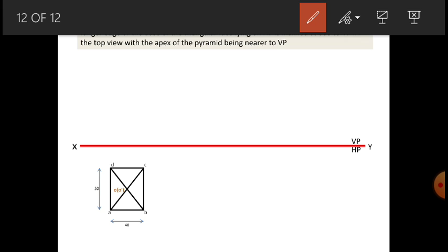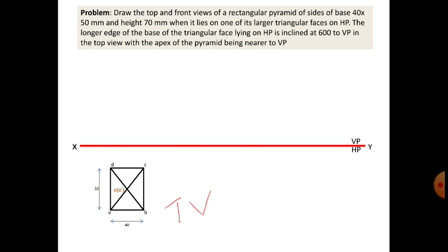Now this is your top view, right? The pyramid has its vertex, or the apex, where all the edges meet at a point, that is O dash. O dash is the point below where your axis line passes through. It is the center of your object. Now we'll bring the front view by projecting the lines AD and BC above the axis and the center line O dash.